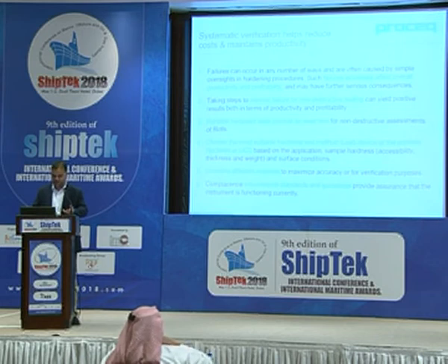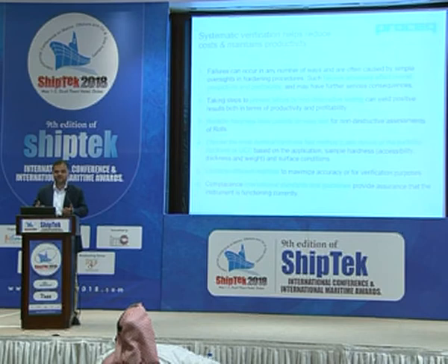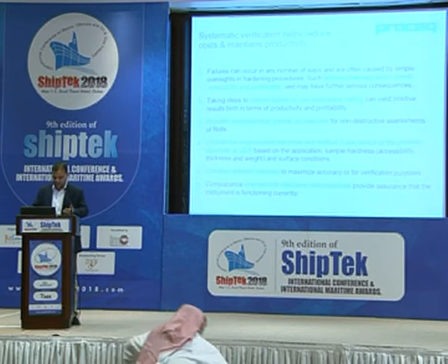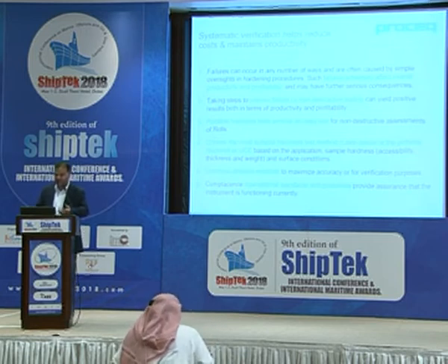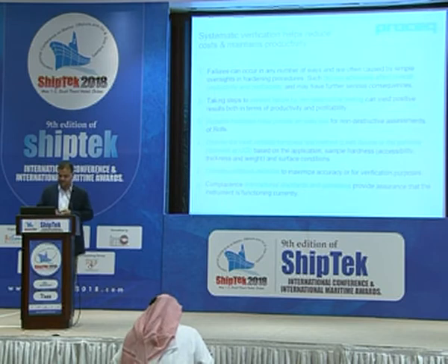For example, choose the most suitable test technique. As I said, for heavy and bulk components, Leeb is the most established technique, giving more reliable, repeatable, consistent data. For very thin samples, portable Rockwell works very well, and especially when it comes to welds and heat-affected zones, the UCI is the most established because precise positioning of the instrument is possible on the welds and the HAZ. So, combining different methods maximizes accuracy of a verification process,